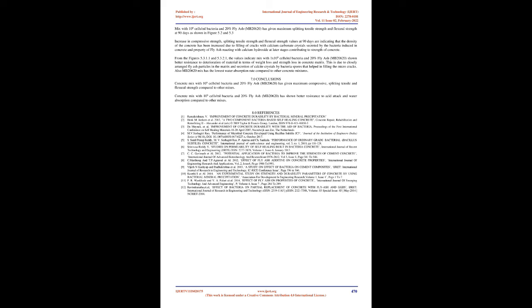Increase in compressive strength, splitting tensile strength and flexural strength values at 90 days are indicating that the density of the concrete has been increased due to filling of cracks with calcium carbonate crystals secreted by the bacteria induced in concrete and property of fly ash reacting with calcium hydroxide at later stages contributing to strength of concrete.